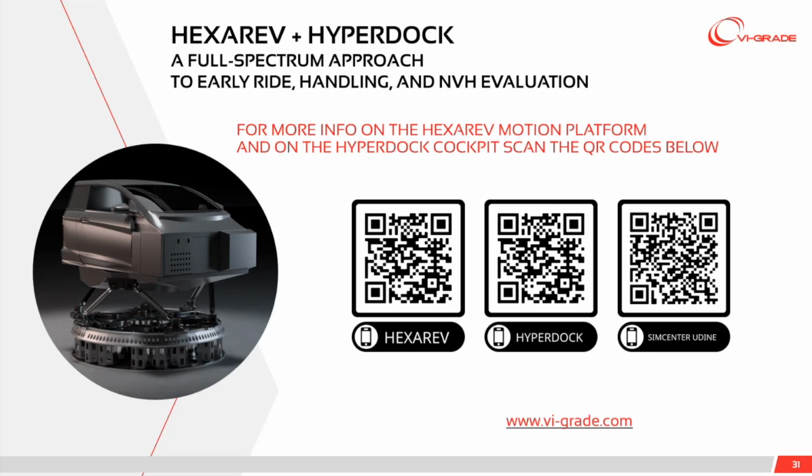The other possibility is that the transfer function is not from the hub acceleration to the local touch point anymore, but from the suspension link force to the touch point. And at that point, you have the bushing in the data which is coming before. So there could be multiple approaches, and every customer should find the better solution based on what they need to evaluate, because of course that's the main thing. It all depends on what needs to be evaluated in that particular situation.